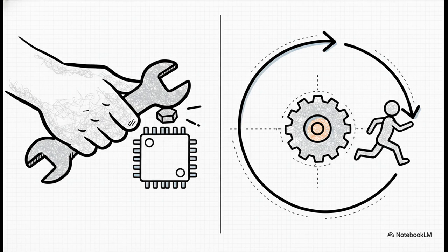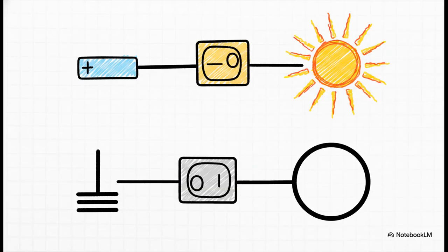Once that setup finishes, we fall right into void loop. This is our infinite processing routine that runs forever, using digitalWrite to actually pull the strings of our hardware. When we send the HIGH command via digitalWrite, the microcontroller outputs the system's logical voltage. For an Arduino Uno, that means pushing a nominal 5 volts relative to ground. And when we command it LOW, it drops that output to exactly 0 volts. Just like that, our software logic is instantly transformed into electrical potential.